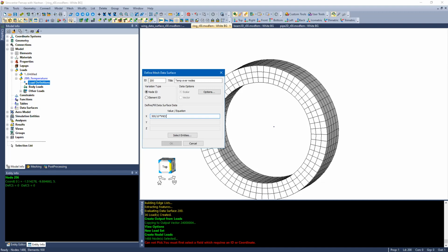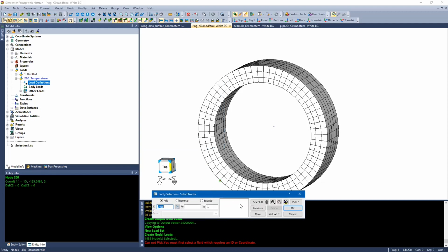And by default, we'll use an exclamation mark to denote a variable, and the I is used as the default for whatever variation you have picked. So the exclamation mark I will loop over all the node IDs in the model that were selected. So to select those IDs, I will do select entity, and again, select all, because I want all the nodes to be used.